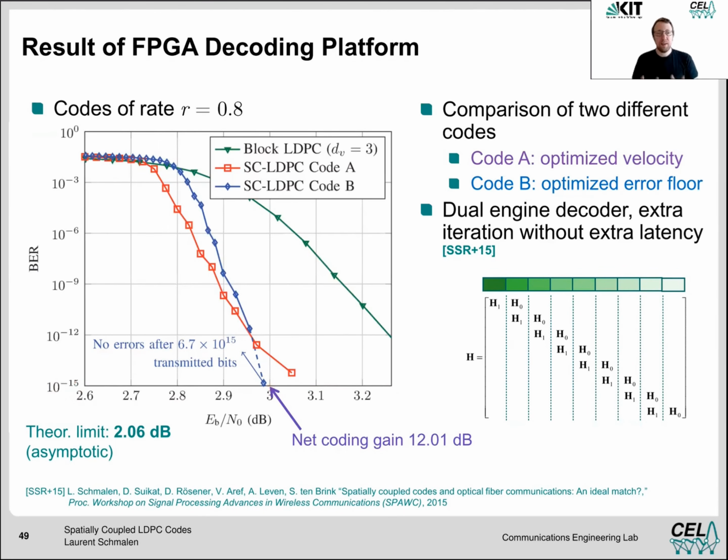And this is a code that has been implemented on a chip that runs with fixed-point operations, that has a strong quantization, and a limited number of operations that you can actually perform. And we are within 1 dB of the capacity. So the asymptotic limit is 2.6 dB, and we are at less than 3 dB. So we are at 1 dB from capacity with a very practical decoder that could be implemented in the field.